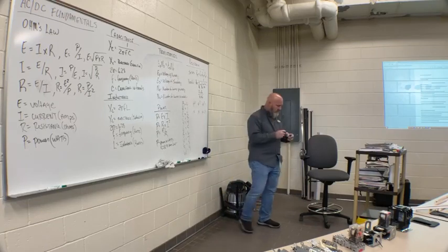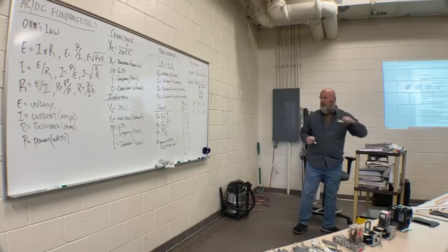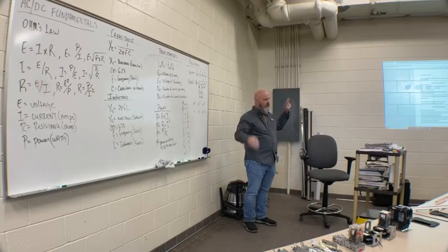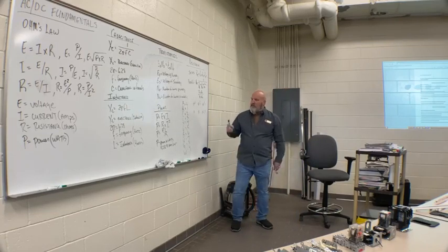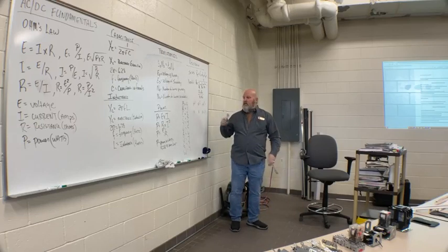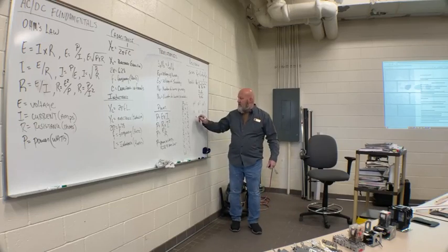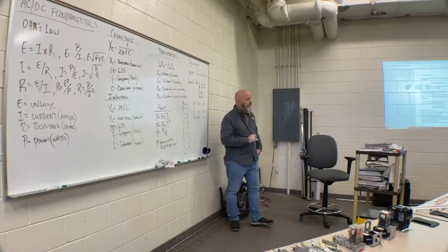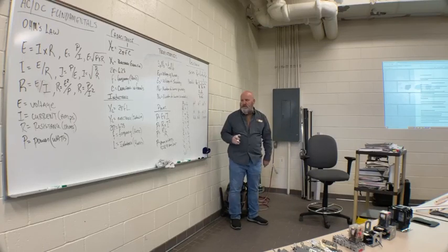Okay, so when you're reading a resistor, you pick the resistor up, and there's three color bands on it. There's actually four. The fourth one is gold or silver, and that's the tolerance. So if I saw a red, red, orange resistor, that's what the color band says.